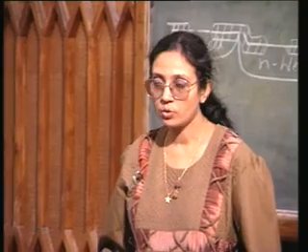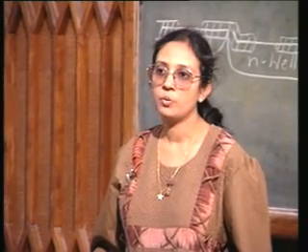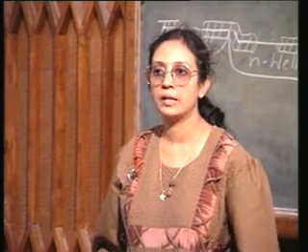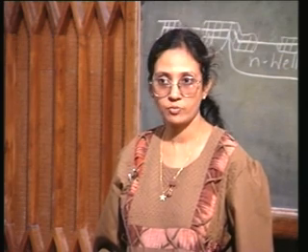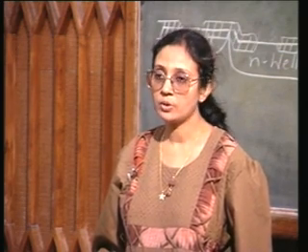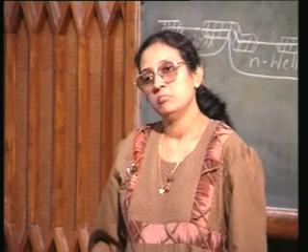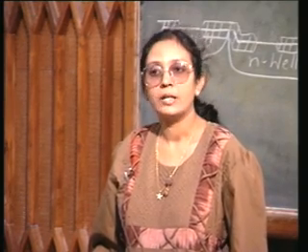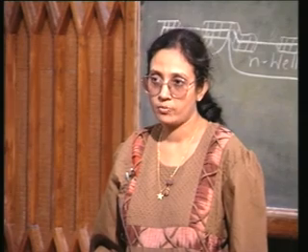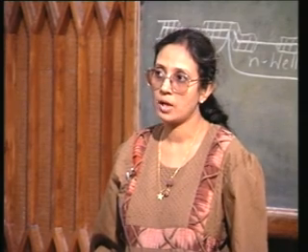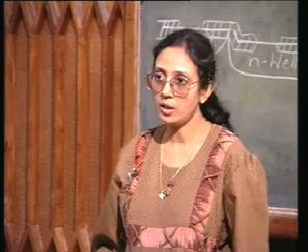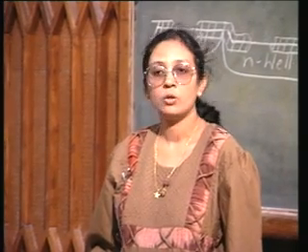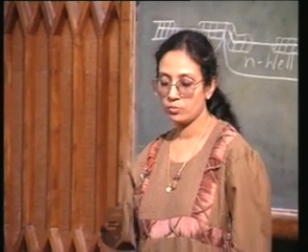We did not have to use a buried layer or an epitaxial layer. So far we only have P well and or N well. If you are having a Twinwell technology, you have both an N well and a P well, otherwise you have one or the other.